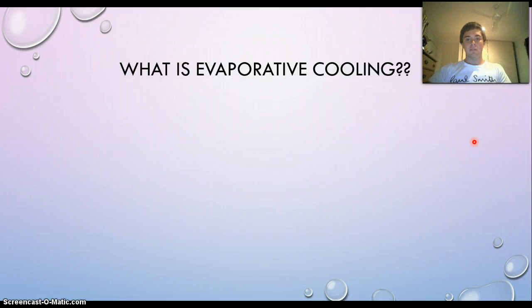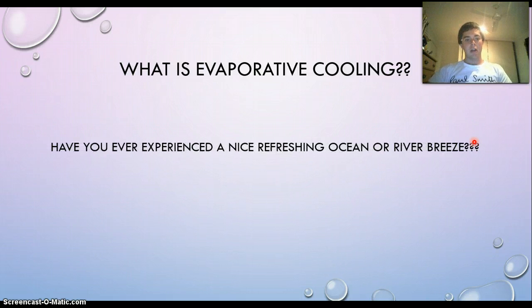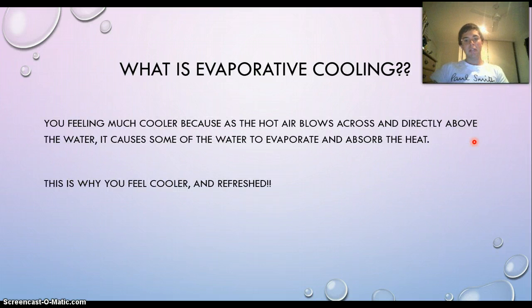So what is evaporative cooling? First of all, I want to ask you the question. Have you ever experienced a nice refreshing ocean or river breeze? Unless you live in the middle of Australia with no rivers close to you, most of you have. You feel much cooler because as the hot air blows across and directly above the water, it causes some of the water to evaporate and absorbs the heat. This is why you feel cool and refreshed, because as the water is absorbed into the air, it absorbs the heat also, which cools the air and adds more moisture to the air too.